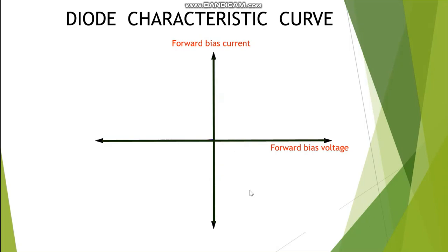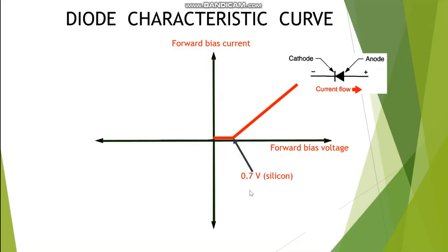Looking at a typical diode characteristic curve for conduction, we see that once we get past the 0.7 volts for silicon, you're going to measure your own tomorrow. It says on the lab, use 0.7 for your value of barrier voltage. But I'm not going to have you do that. Do not use that. I am requiring you to measure your own diode and replace the value where it says use 0.7, scratch that out and put in what your barrier potential is. I'm going to show you how to read that in a minute.